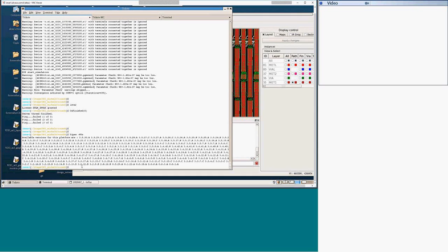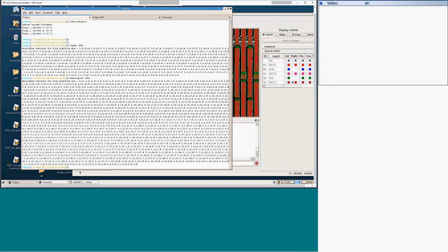For Smart Spice, I'm afraid you may need, again, Smart Spice minus VBS. You may need this version 427.3a. So why is it so? Because you have some devices that we did not support in the parsing and use Spice parser.